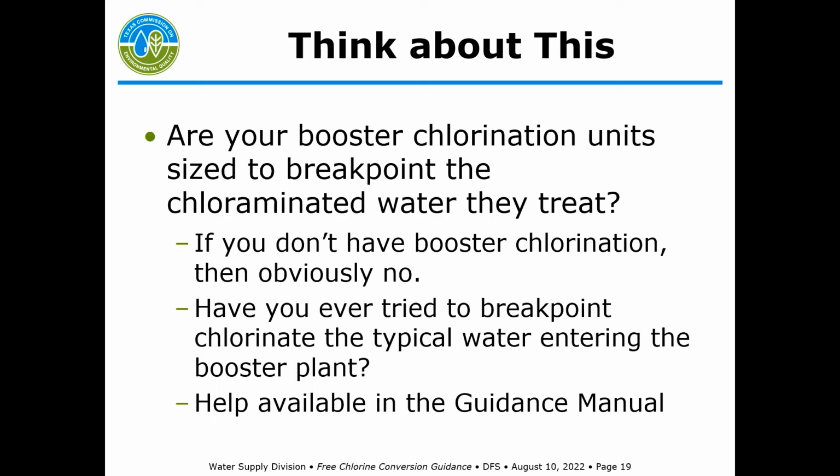Leaving those sediments in the distribution system can actually promote nitrification. So it's a good idea when you're doing the free chlorine conversion, just get everything cleaned out of there so that you're starting without a bunch of sediments where bacteria can multiply. So kind of think about this question.